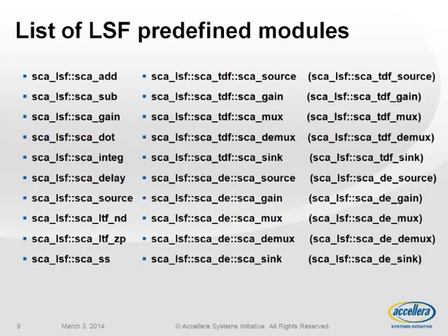What is the complete list of the predefined LSF modules? You have the possibility of adding values with weighted coefficients, subtraction, multiplication, derivation, integration, delay, the possibility to have sources, the possibility to also have LSF versions of LTF with numerator, denominator, and zero pole. You also have the possibility to have state space equations in LSF.